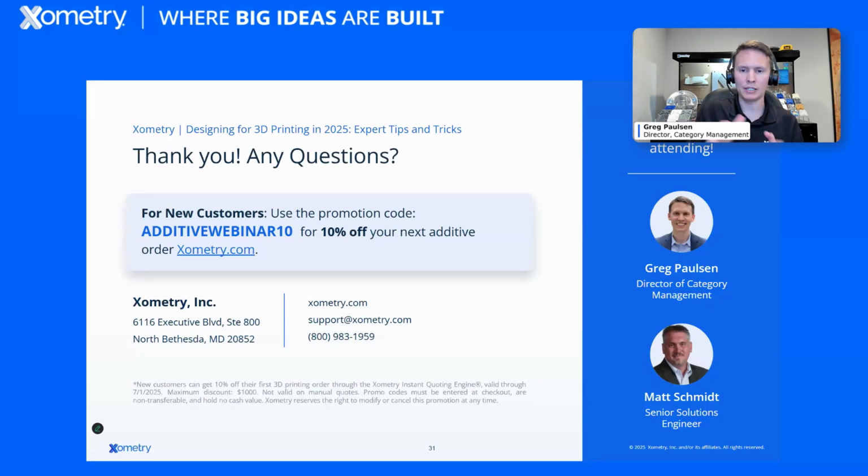So split and bond on that side, one of the things I had to build one time was a really large round piece. And it just happened to be outside of the Fortis FDM platform. So Fortis goes 36 inches by 24 inches on the planar side, and it was beyond that. Instead of tilting up on the side, which may have affected my roundness, the roundness was more secure by doing a split and bond. So sometimes just spinning the CAD will help us find the right solution because you're outside of the hypotheticals and you're into real application. So uploading that CAD is super important.